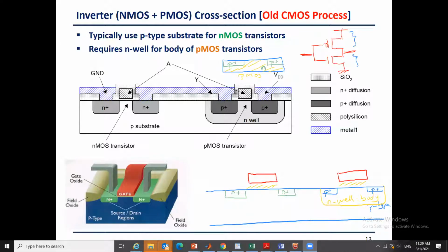Okay, so I need to put a layer of insulator and then do what? And then drill this insulator. I will put an insulator everywhere, and then I'm going to drill the insulator so that I end up drawing a pillar or a contact, and then I draw a connection between the contacts. So it happens in 2 steps. First I drill down, fill, then I draw the road that is connecting those two. This connects those two drains together.